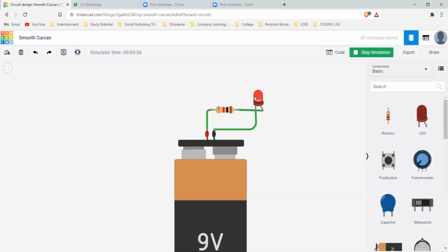So before that happens, you need to actually know which color is for what. So we basically define 4 major colors in TinkerCad. One is the positive, second, the negative, third, the input, and fourth, the output. There are many other special wires that we need, but we do not currently need them. So these are 4 wires that we are going to use.